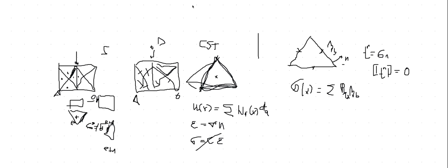Basically, to enhance this behavior so that I can obtain a much better response for dynamics, where the constant strain triangle is no longer optimal, because introducing these jumps in the stresses gives lots of false information in my dynamics, and every time perturbs the wave propagation computation result, giving me jumps that are not supposed to be there. So that is really the idea that we're trying to enforce here.